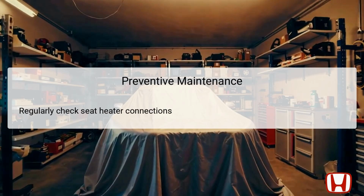Preventive maintenance is a strategic approach to avoid the recurrence of issues like DTC B1C55 in the future. Regular checks on the seat heater connections and ensuring that wires are free from wear, corrosion, or loose fittings can significantly reduce the risk of electrical failures. It is advisable to periodically inspect the function of the seat heater to ensure that it activates as expected, especially during the colder months.